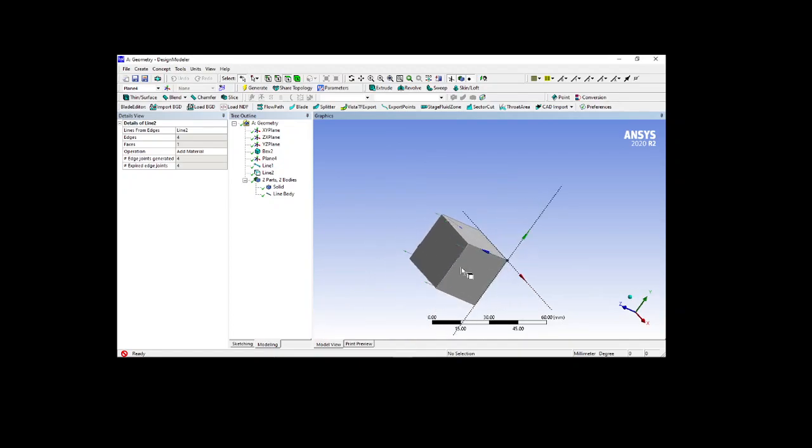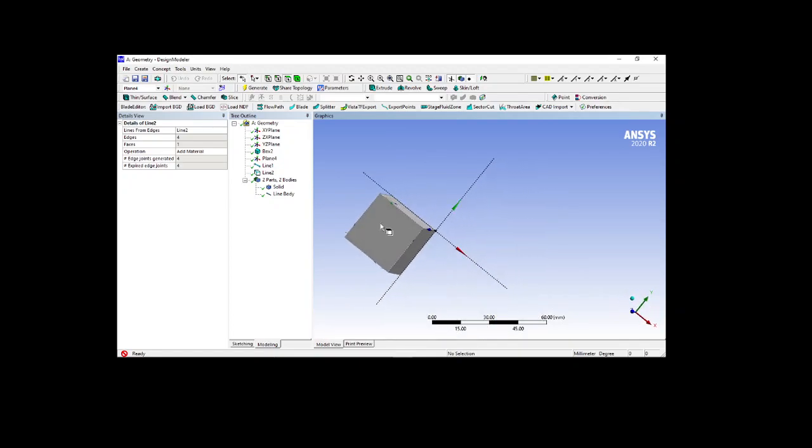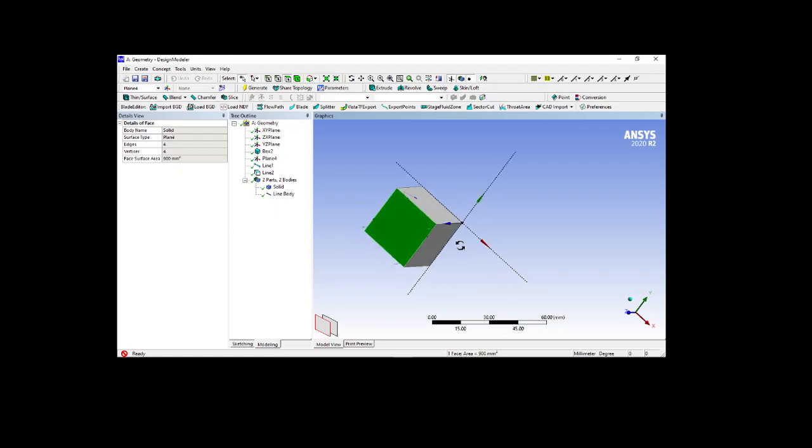This becomes the virtual face. This virtual face has a different definition than the actual one. Now we come across the concept of the 3D curve split line. This split line helps us divide the line. If I press here, then this line will get split.